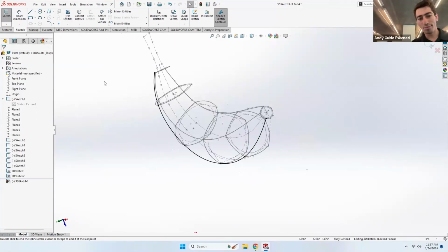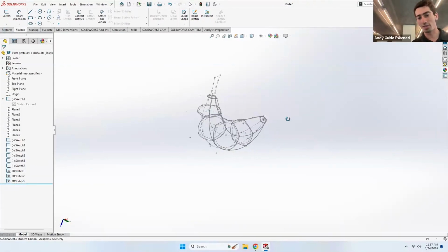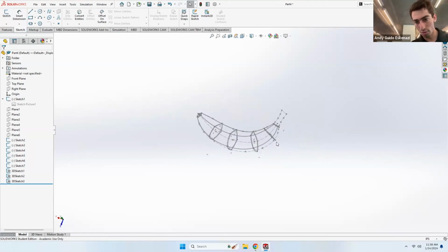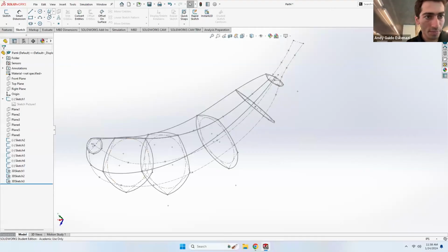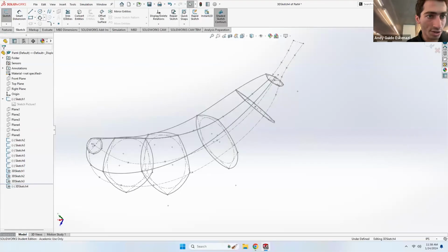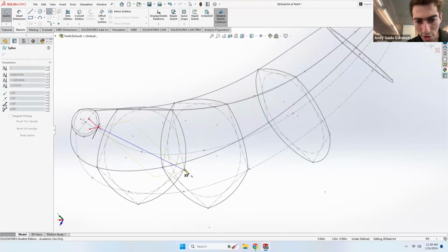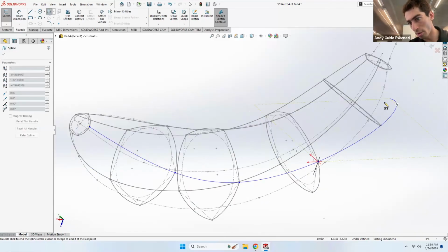And in essence, if you were to look at the very fundamental aspects of a 3D geometry, it's all wires, like I'm drawing you right now. Now I need to do one more wire, two more wires. Actually, hold on. 3D sketch, wires. So why 3D sketches? Because there's obviously no plane that would traverse all of these points that I'm connecting over here.